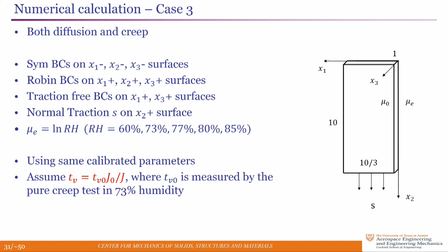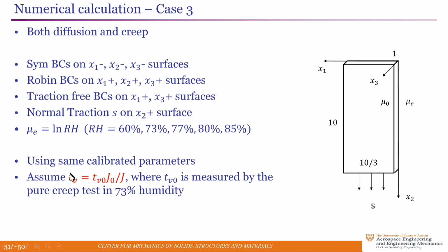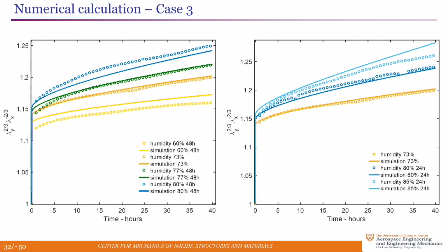There's one more thing to do for the cases when there's both mechanical loading and hydro loading. Could we represent everything? And it turns out you can. This is the same program. The symbols are experiments, the solid lines are the fits. But this time, we have to change the viscous time constant for each one of the swollen specimens by a factor that depended just on the swelling ratio. So if I increase the volume by swelling to a certain volume, creep process will speed up in proportion to that increase in volume. That's what this says. The time constant of the viscous process multiplied by the volume of the specimen is constant over the entire time. And so we're able to capture the poroviscoelastic response with this two-potential model fairly easily, accurately.